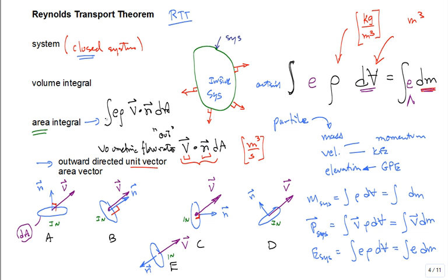E. This same E down here, which is our energy per unit mass. Energy per unit mass, right? So once we get this area integral, we can get the volumetric flow rate, we can get the mass flow rate, we can get the energy flow rate that's crossing that boundary because it's going with the mass. There can be a shaft energy flow rate across the boundary later, and it could be a heat transfer energy flow rate across a boundary later. But right now, you can have energy flow with the mass.